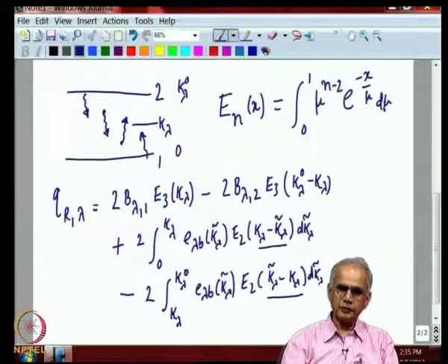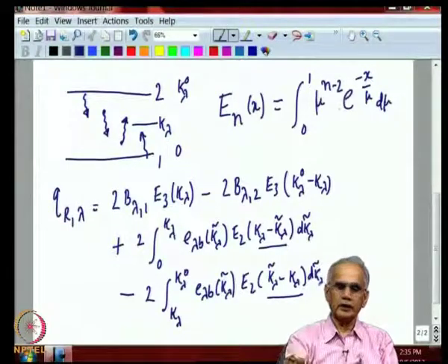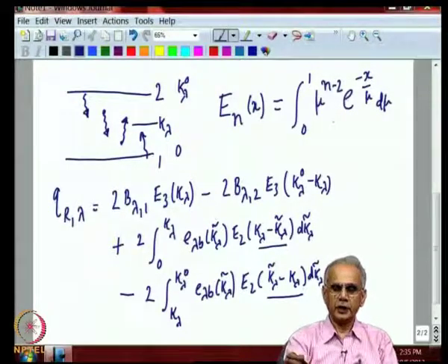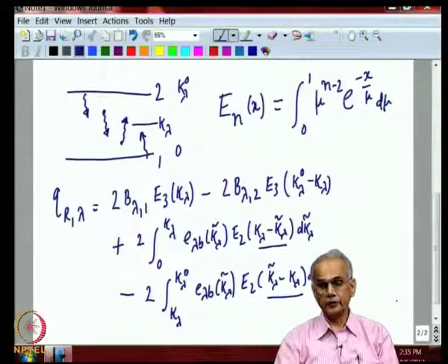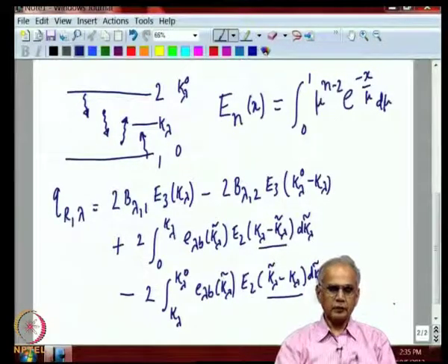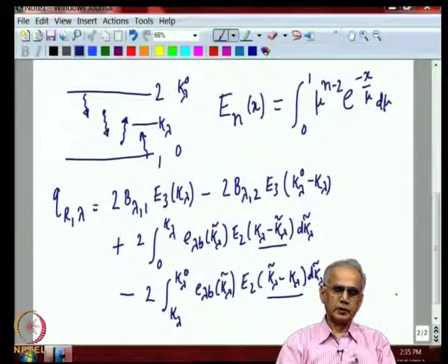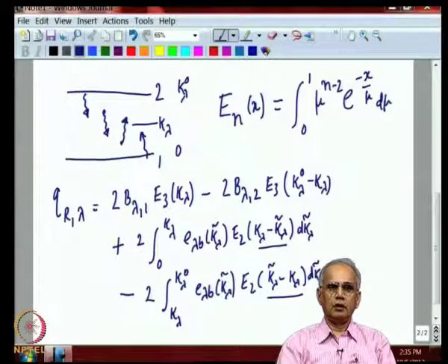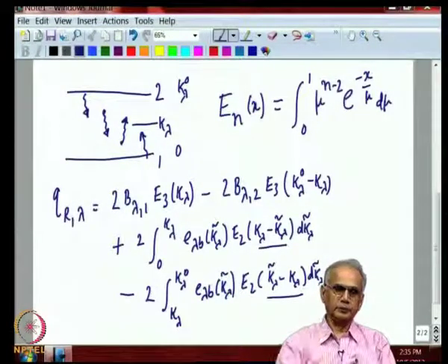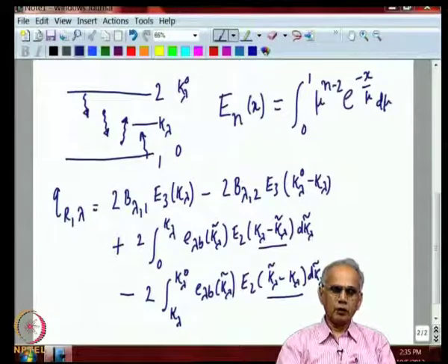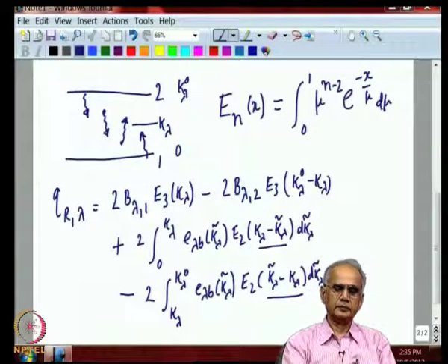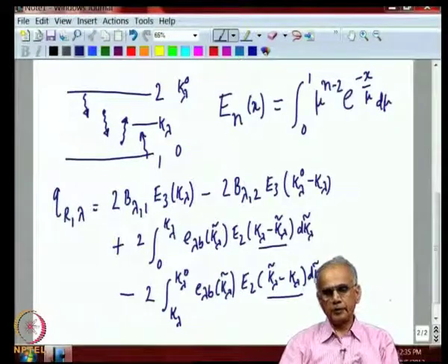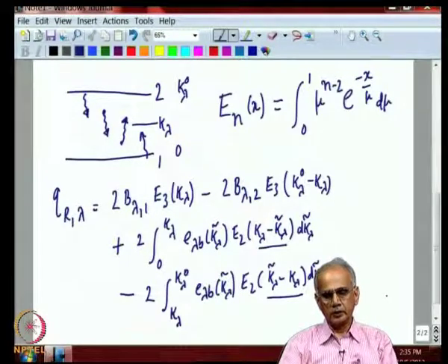The major challenge we face is not the angular integration. That is very straightforward, as I said, can be done by any computer very easily. The major challenge we face in solving the equation is the fact that if you want to know the temperature distribution of a gas in an enclosure, then the unknown temperature variation is inside the integral here. So, this is a peculiarity in radiant heat transfer.